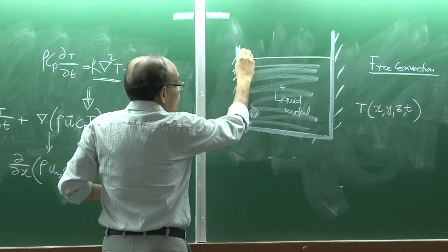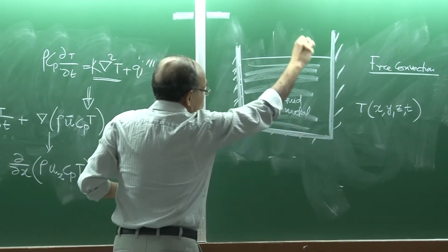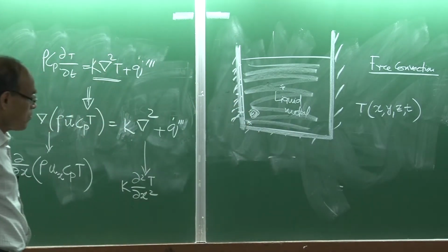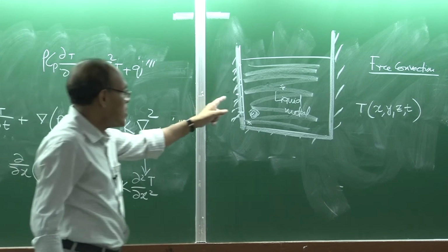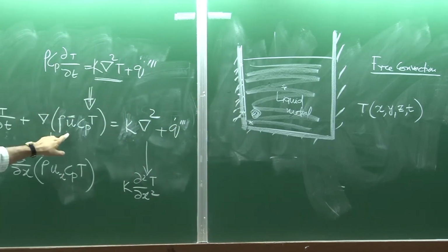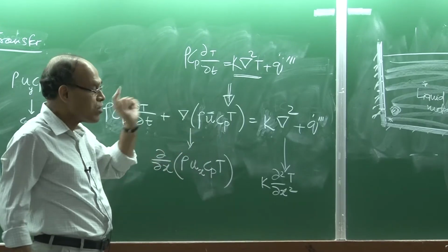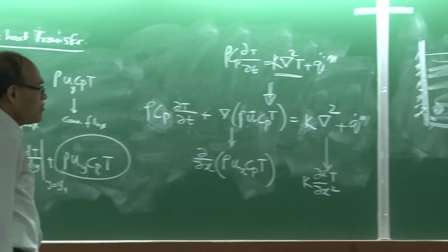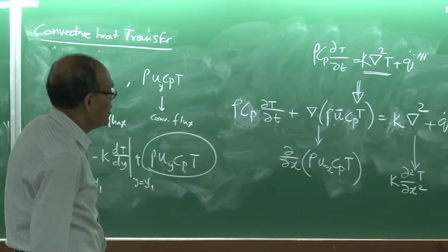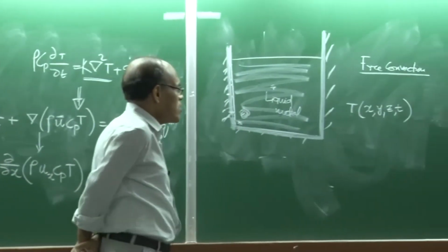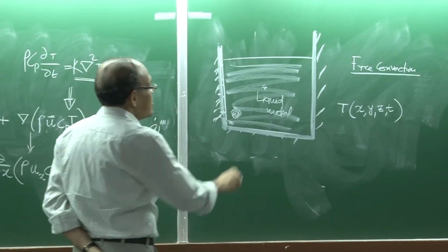But nonetheless, if you want to treat this as an entire domain, in that case you will require a boundary temperature here or a boundary heat flux here. So, the same kind of boundary conditions will be applicable here, what I have discussed in the context of convection. So, it is not going to be different.